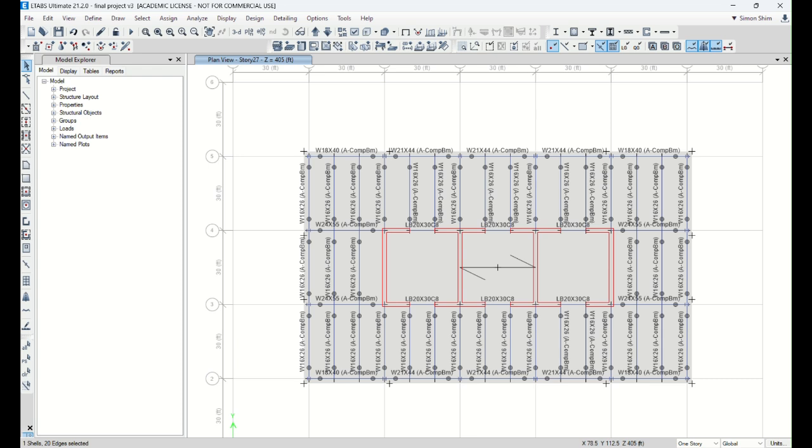Got it? The World Trade Center, which actually collapsed, had the same system. The girder is very huge, and the column spacing is very closely spaced, less than 10 feet. There is a series of columns because they try to engage the whole perimeter moment frame as part of the lateral system, because they didn't have any concrete core wall. They may have a few braced frames, but that's the point.